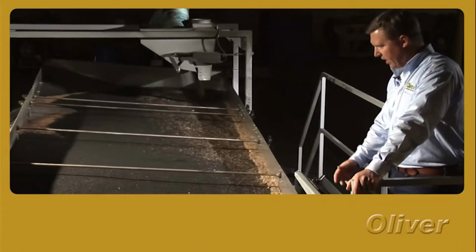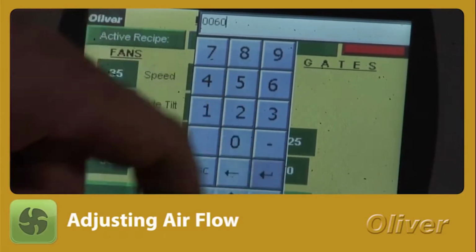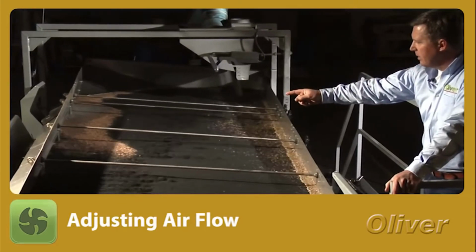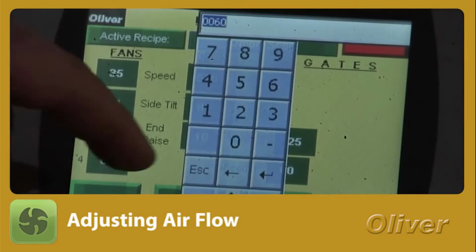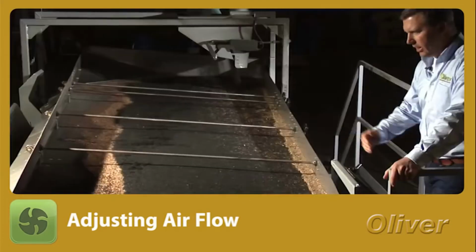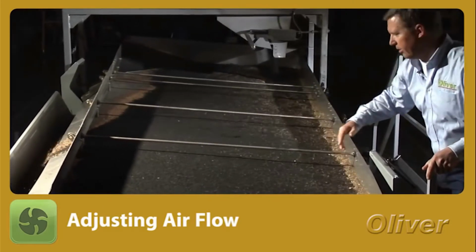If you look at something in this situation where you create too much air, as in this case, you'll see your separation goes to pot. We've got heavy material coming down into our light material. I can adjust that very simply by going back to the same air setting I had previously. You'll see the heavy product sink back to the deck and move back uphill and react as a heavy particle.